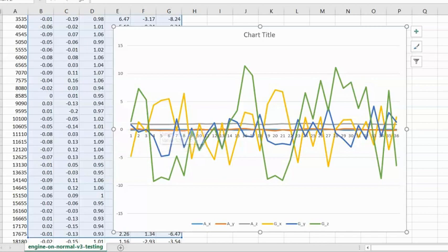Whereas the gray one, which is the acceleration on the z-axis, is almost having a value of 1. This indicates 1g, and this is normal, and this is what we are expecting due to the Earth's gravity. Having said that, this doesn't mean that there are no slight oscillations around those values, which will be of interest later using the spectral analysis tools.